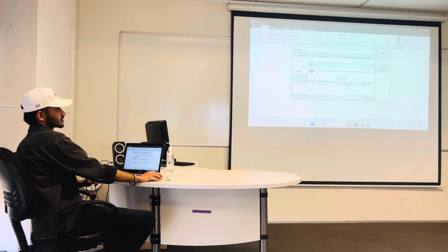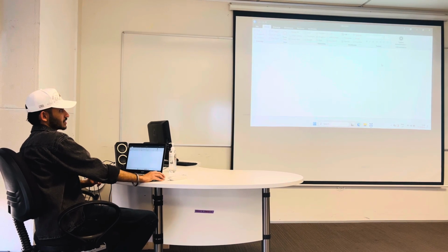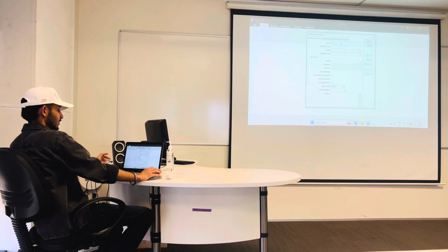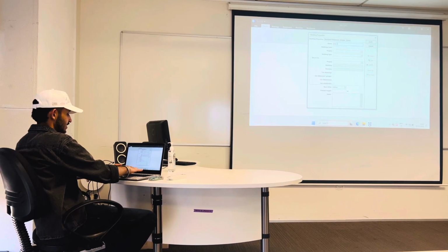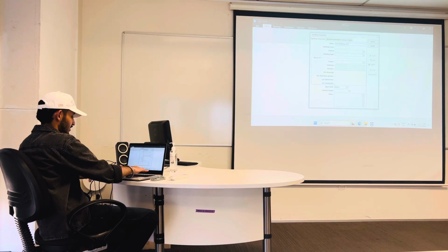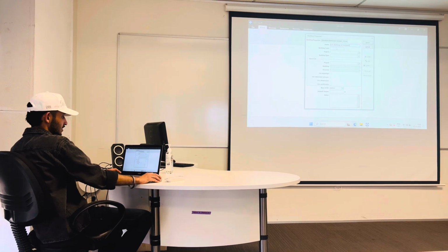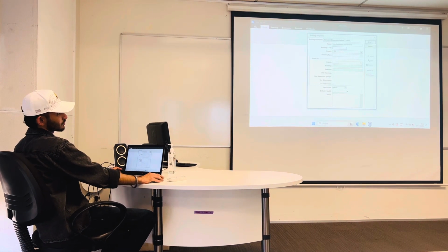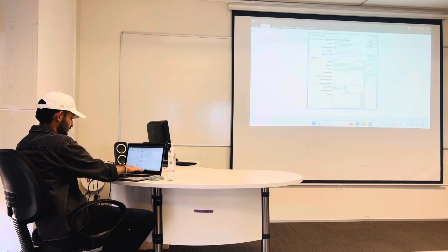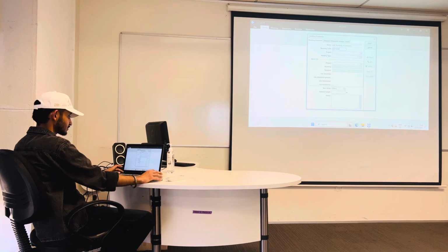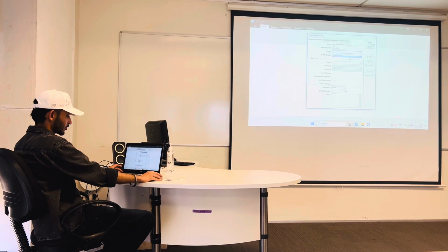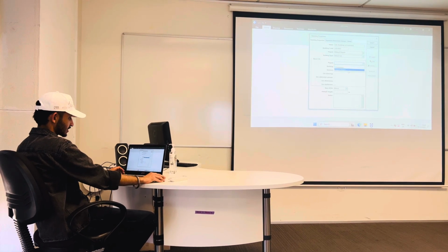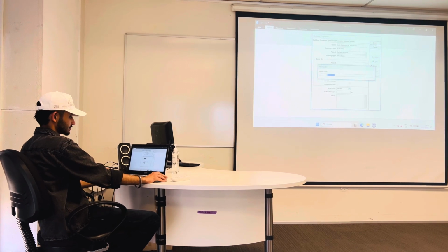you have to click on new project, new building, and then you insert the building properties or the project details. For example, I put here ACTS building at Oakland. The building code we can put our building code, but here we put our student ID. Project type, default project. Building type is mixed use, and the project default. Then we insert.